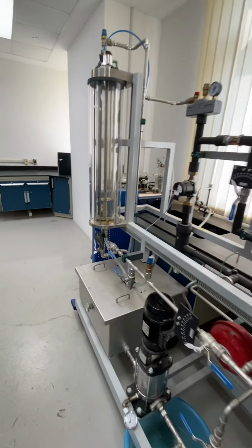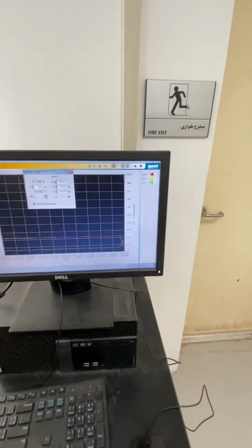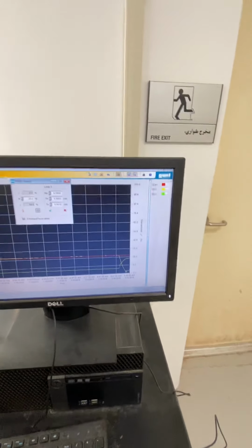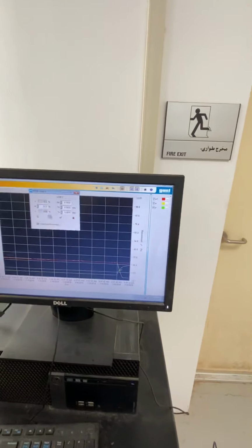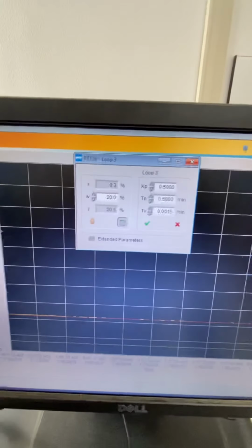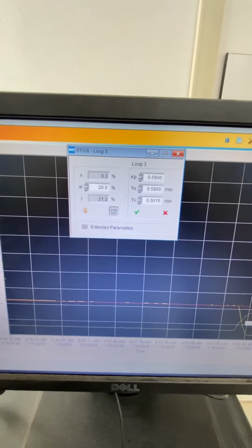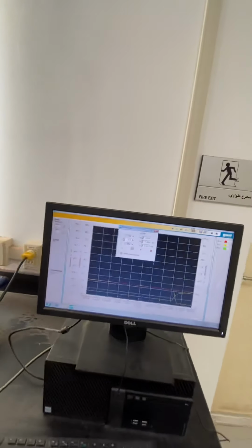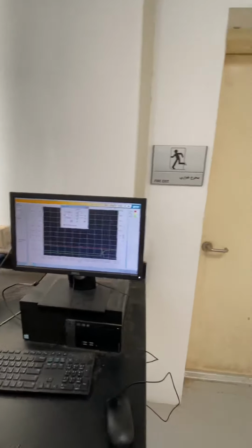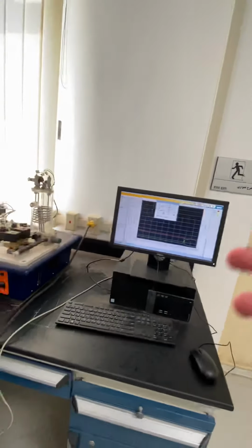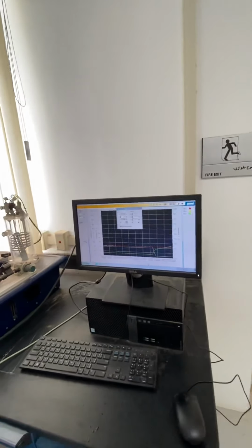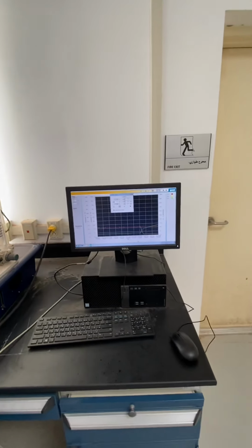You see that the tank is getting empty right now, and you'll see that the process value is now getting almost 0%, and the output signal started to increase. Look at it right now. It shows 20%, 21, and it is increasing, and it will continue to increase, guys, until it reaches the saturation limit, which is in this case 100%. So the feedback control system actually doesn't know what is the nature of the disturbance that has been introduced to the system.